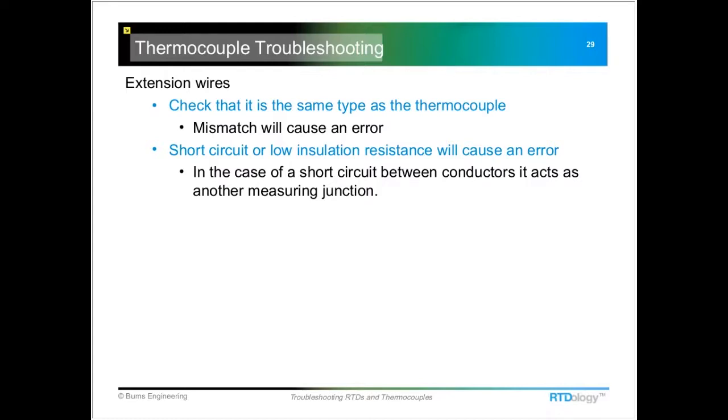That one can sometimes be difficult to find. If you use plastic insulation on the conductors, that's usually not an issue. I have seen cases where, with fiberglass insulation, stuff can get in there and actually short them out. The insulation still looks okay, but it's porous, and so moisture or conductive dust can cause an issue.